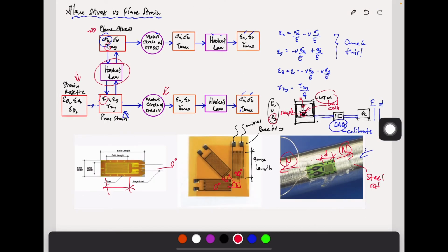The universal testing machine typically uses the load cell. There are many load cells installed in this sensor right here, so it is very sensitive. Be careful when you are handling the machine. You don't want to go beyond. If the load cell is rated for 50 kilonewton, you need to prepare your sample so that it doesn't exceed this value of 50 kilonewton.